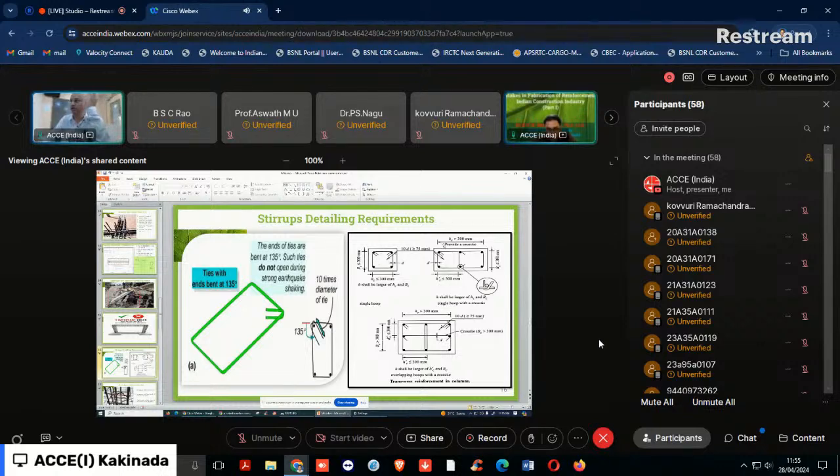That is, whenever the spacing between the two outer bars is more than 300 mm, this outer tie is not effective. We have to provide an inside link also, that is in the form of this. This should actually not be a 45 degrees tie. It should be in the form of a hand hook. This is one of the mistakes that generally takes place on the site.